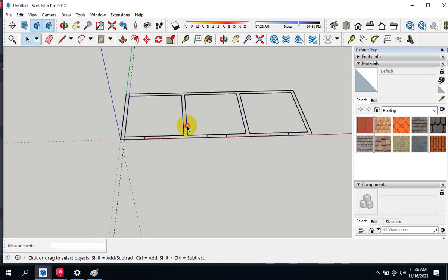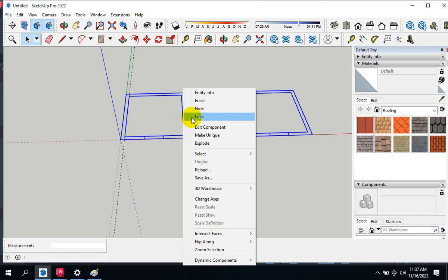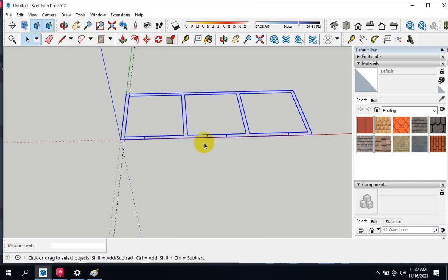So what you do, click on the mark about there. If you click, it's like one single object. Just left click, not right click. You see, it's like an entire block form. So we need to explode it. So right click, second click is explode.